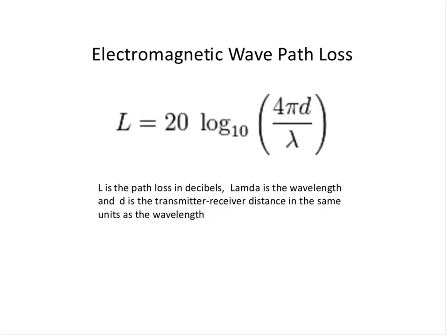And it's a square relationship because it's 20 log, so you take 2 times 10, so you put the 2 up, it's a square relationship. So the actual range relationship is a square root relationship. This is why sub-gigahertz communication is very, very cool. You can go much farther. Yes, you get fewer bits per second, and I'll explain why in just a sec, but you get better range. So 900 megahertz is sweeter than 2.4 gigahertz.